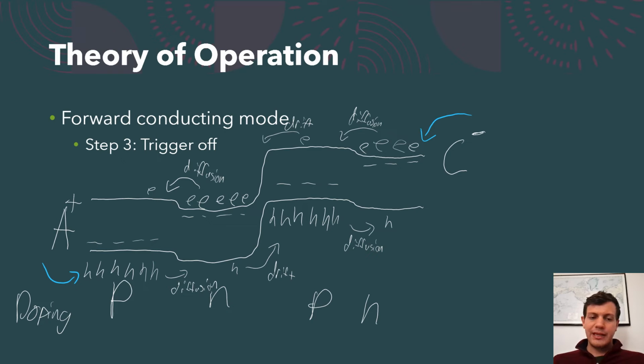or another floating gate. So if we imagine we're a hole in this first P region, we've been injected from the anode, and we're going to diffuse into this N-doped region, which now has a pretty high Fermi level. So now that we're here, we're going to drift our way down this potential, high voltage, low voltage, and then diffuse into this N-doped region at the end, where we're going to recombine with electrons from electron donors, which are going to get replenished right away from the source.